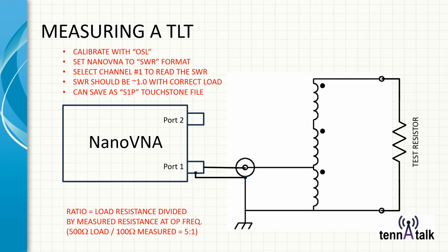That can be imported literally by dragging and dropping it from your desktop into SimSmith as the source scan file of your antenna. And then you'd have a scan of your antenna from, say, 3 to 30 megahertz in SimSmith that you can do all kinds of experiments with in simulation rather than having to mess around with real antennas.